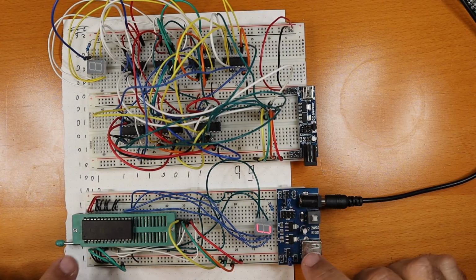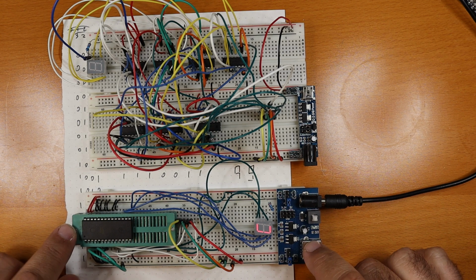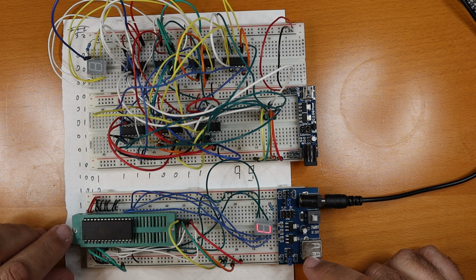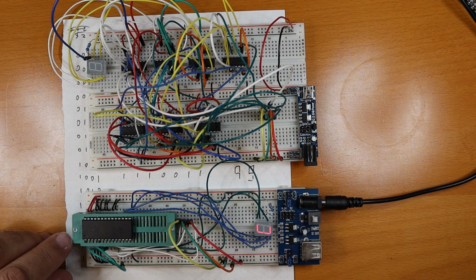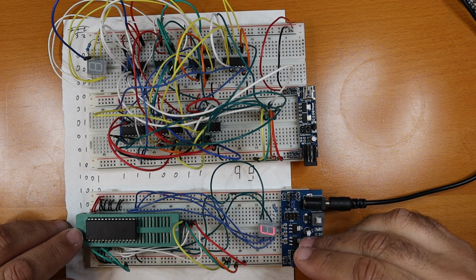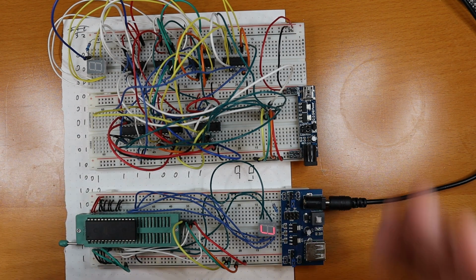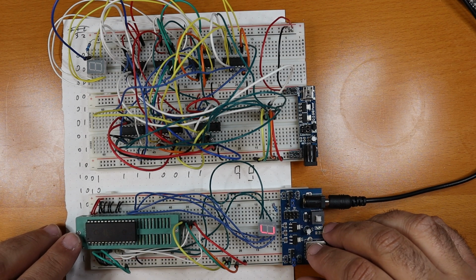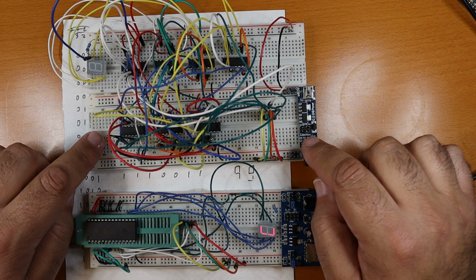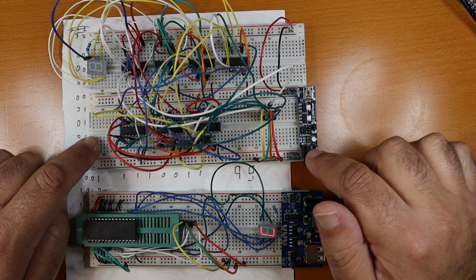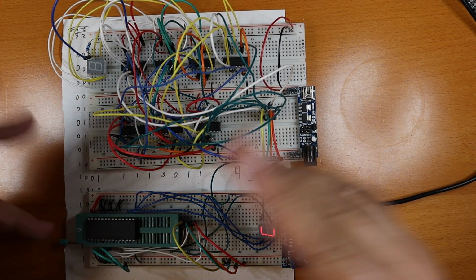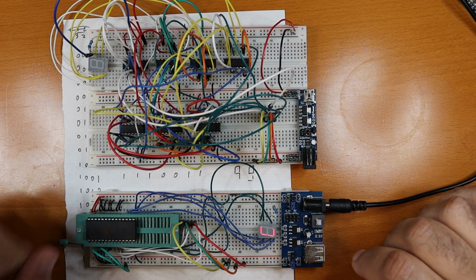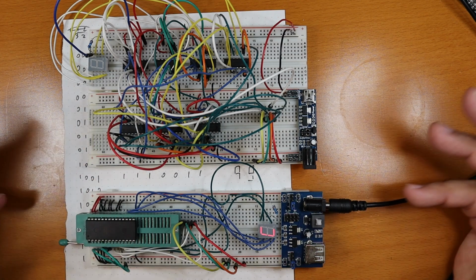And the problem with hazards with ROM is that they're unanalyzable. You cannot analyze the circuit to understand when hazards happen. And the other problem is that they're unsolvable. There's nothing you can do in order to solve them. And both are not true for discrete logic. You can both analyze it for hazards and solve them by adding more gates in discrete logic. So this has a huge amount of downsides.